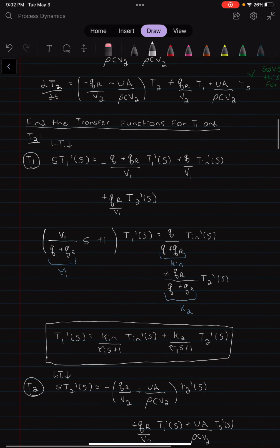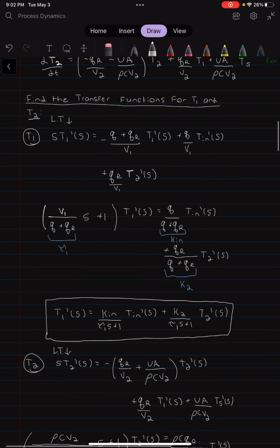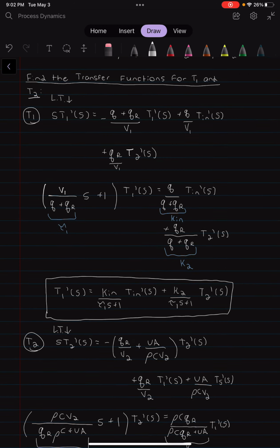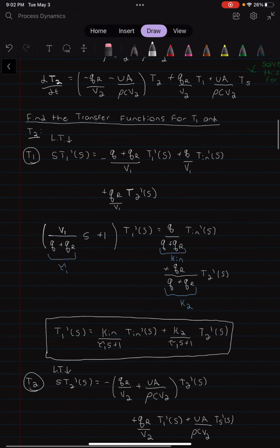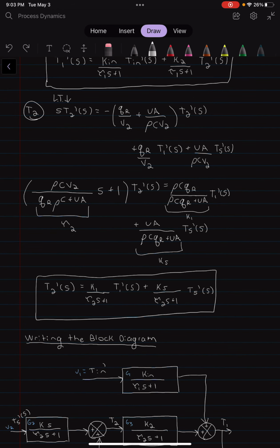although we can pull out constants. Then once we have our energy balances, you linearize it to get the transfer functions to determine how the temperatures T1 and T2 relate to each other. For our first tank, we just linearize our energy balance after taking the Laplace transform, and then we do the same for tank 2, with slightly different numbers. We can also figure out that tau 2 is equal to this portion, and then our other process variables are equal to different portions.